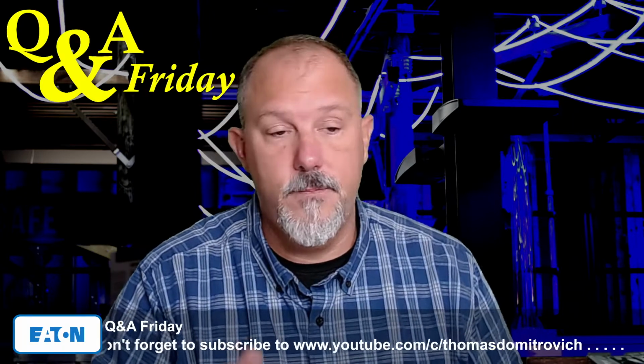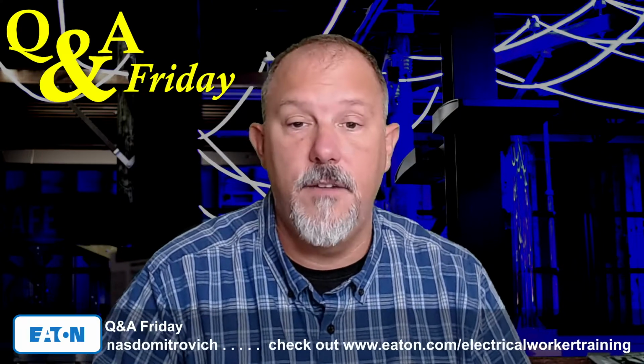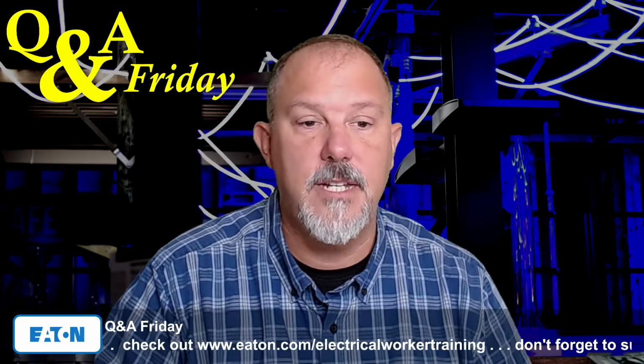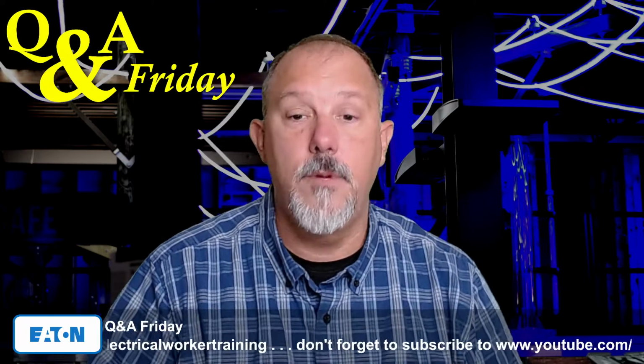And then JW went on to say, isn't the reason for the rule concerning overcurrent failure of the appliance? And if so, what is the reason for requiring the protection ahead of the outlet? I think this could cause a problem because putting a GFCI device closer to the equipment that it protects is said to reduce the chance of nuisance tripping. And I would disagree with that.